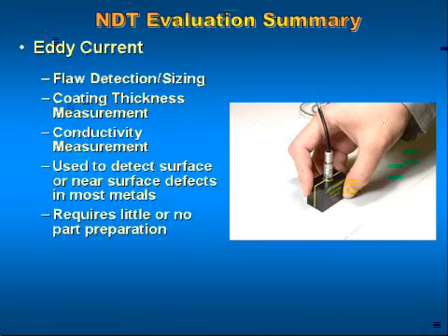It's used to detect surface or near surface defects in most metals, and the beauty of eddy current testing is that it requires little or no part preparation.